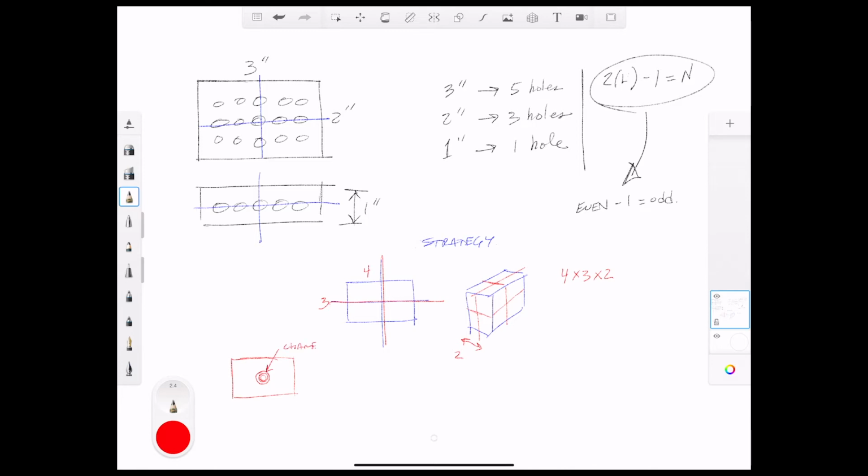Chamfer. And the size of that circle for these 3-2-1 blocks is going to be 0.035 inches. All right. And then I'm going to put a chamfer on there, a small chamfer, 40 thousandths. All right.